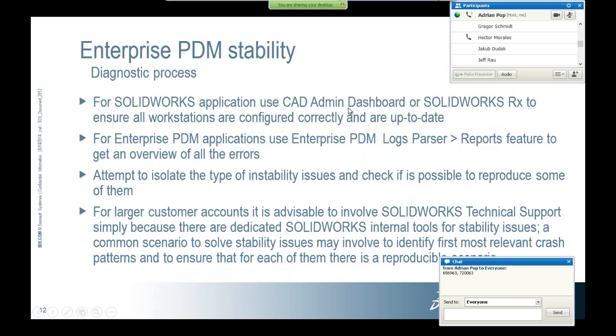What is the diagnosis process when we deal with stability issues? First of all, as I said, you should focus on the SolidWorks product. Maybe you could use SolidWorks RX to make a diagnostic of this CAD admin dashboard. It's important that everything is up to date and that they don't have conflicts, especially with the .NET Framework. For other non-SolidWorks products used for 3D design, you need to check with their support, whatever they have, to solve, analyze, and monitor crashes.